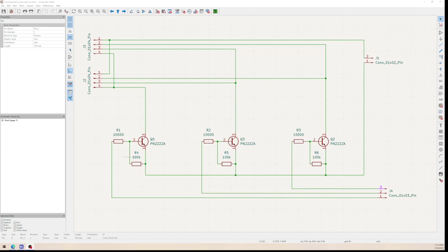Hey guys, so I've gotten some questions from a couple different people on the actual schematic for the common anode to common cathode converter. So I'm going to take you through that quickly right now so that you have an idea what it is. There's about 5 key components. There's your connector with your power and ground. There is your connector that supplies the red, green, blue RGB signal. There is the resistor transistor combos for each color, and I'll get into that in a second. And then there's 2 parallel connections that allow you to connect 2 parallel LED circuits to this particular schematic.